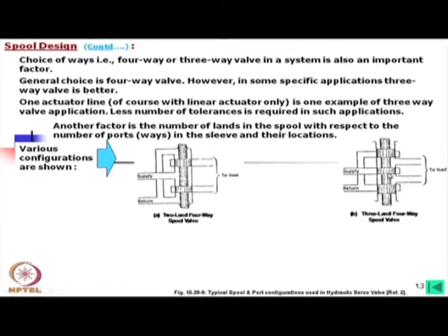When we are moving in this direction, the oil is going like this and the return oil is going back through this path. Okay. And if I move in the opposite direction, this will be opposite. So, now there is a question that why we should go for this. We can make this very simple, but we will see that these two have some differences also,